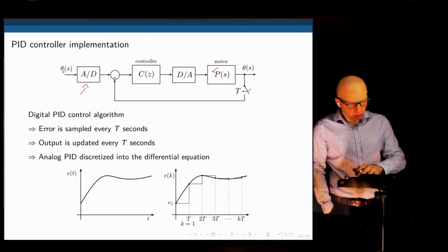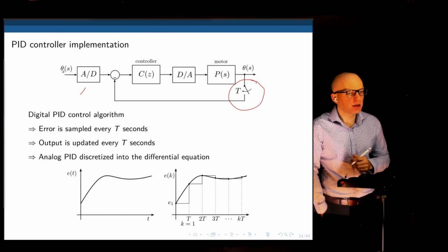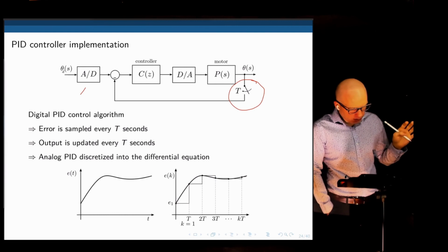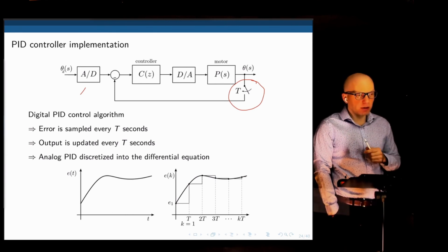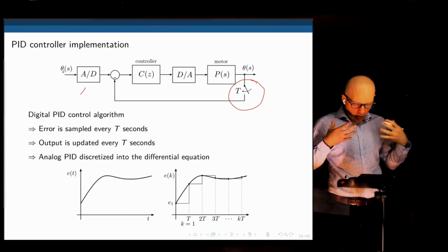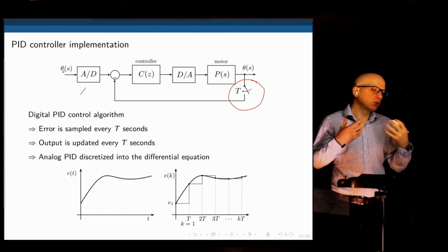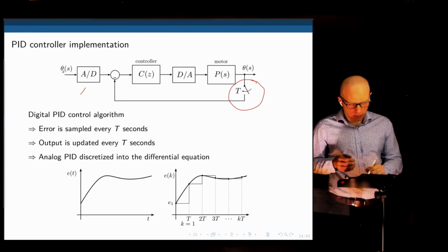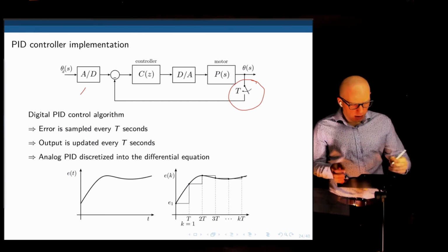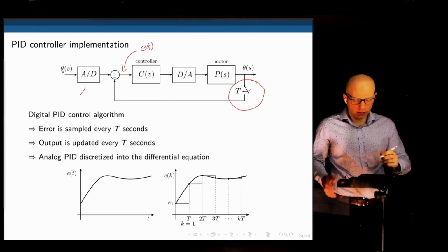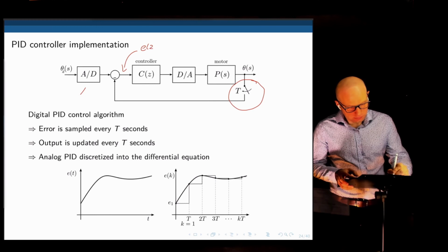This is position control. And now we notice this gate here, that is the sampling gate. This means that it will open and close every T seconds. T is the sampling time. We are discretizing the input. So if we consider the system to be continuous, in the way we did in control systems, the signal that interests us here is the error. That's the input to the controller. This would be R of Z.